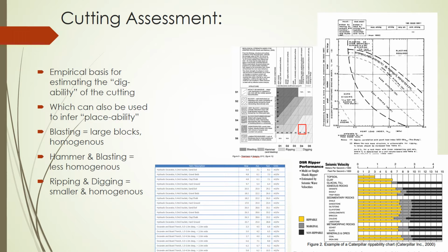That's based on a visual method. Then you've also got Pettifer and Fookes, which is the upper right, which requires a little bit more geological data, but you can balance it and try to estimate your digging methods based on those. And then you can use those to select your machinery, and then estimate your digging and ripping rates and your productivity rates from other various sources.